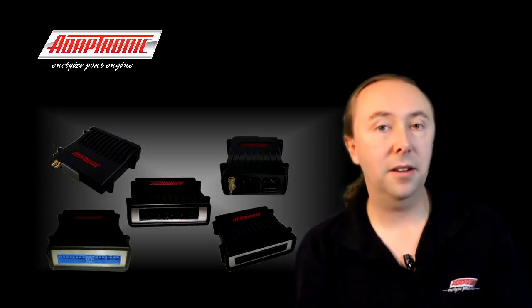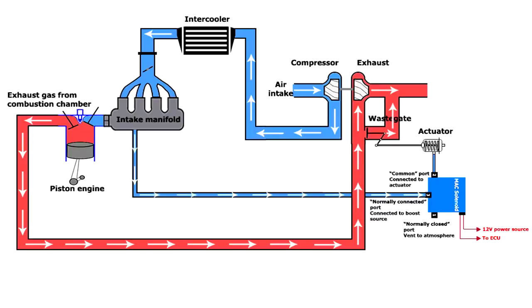Now I'm just going to talk about a common mistake. I believe it's a mistake that people make, which is to source the actuator reference pressure from the inlet manifold instead of from the compressor exit or some other part before the throttle body. So what it means is that the actuator will try to regulate the pressure that it sees at its input port, because that's what closed loop systems do. And so if you take the pressure reference from the inlet manifold instead, then even when you're at part throttle, the actuator will still try and get the inlet manifold to that same target boost.